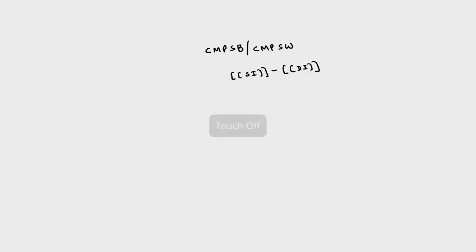Now, again you have not to perform this repeatedly, so you have to use the same thing. Suppose I write MOV SI, 5000H, MOV DI, 6000H. I want to compare 100 decimal data, so I take CX with the hexadecimal equivalent of 100, which is 0064H.